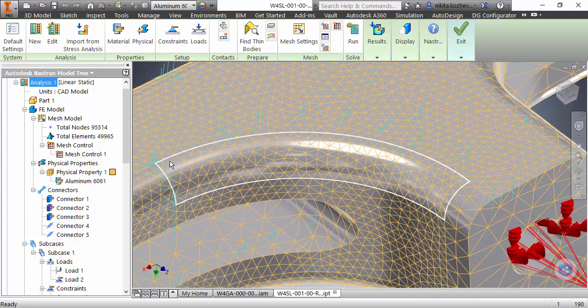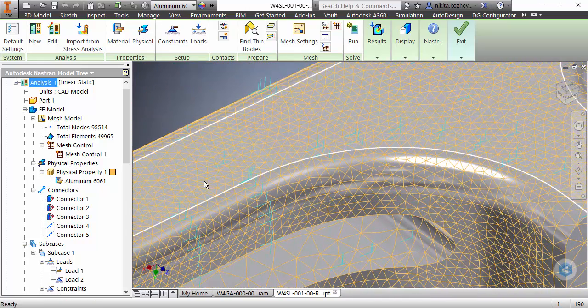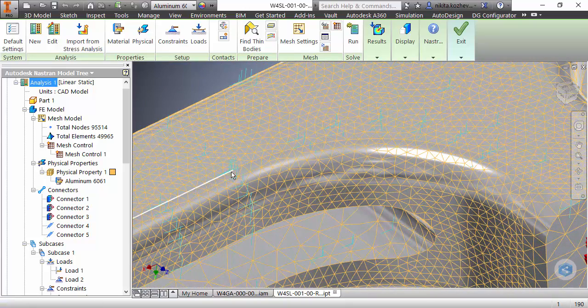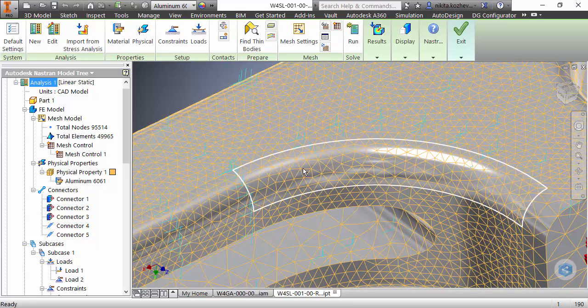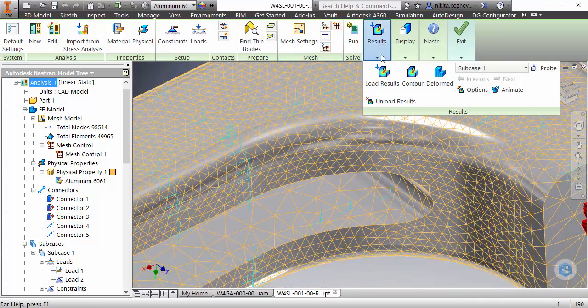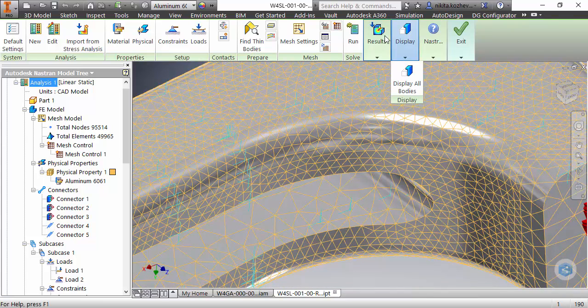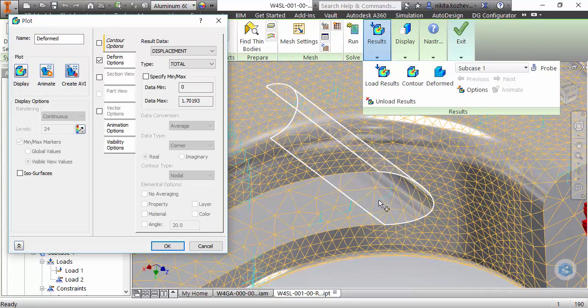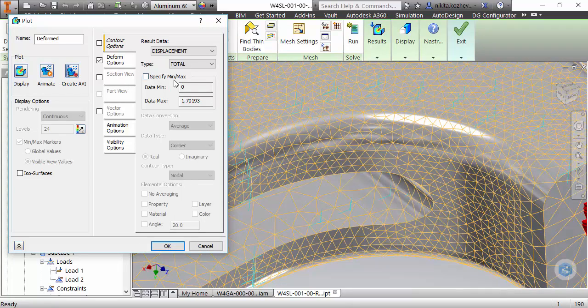Therefore, if we have any loads or other factors that can potentially change the stress picture very rapidly from one point to another, you always need to think about more accurate mesh or much higher mesh resolution in order to represent those rapid changes. And as you can see here, we are talking about this particular thing.